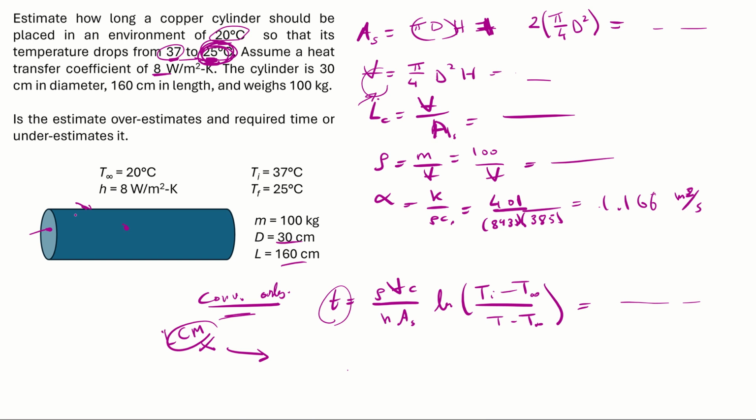If it's at the surface, then the coldest would be the farthest point, and you have to have the plane wall and the cylinder solutions multiplying each other, like a multi-dimensional effect. But this is why I said let's solve it using the lumped capacitance method. I hope this helps. I'll upload a couple more problems maybe about chapter 3 and chapter 2.